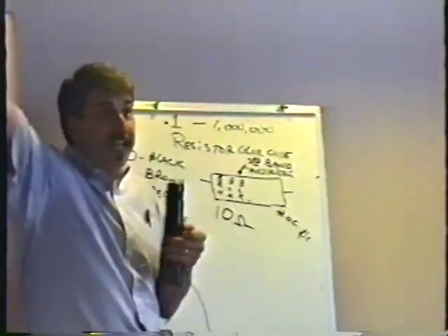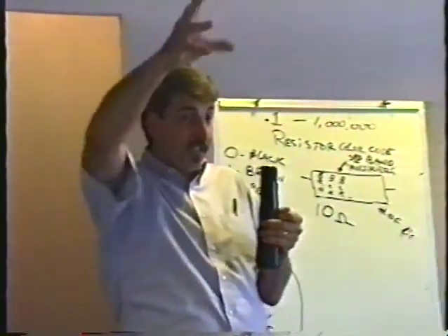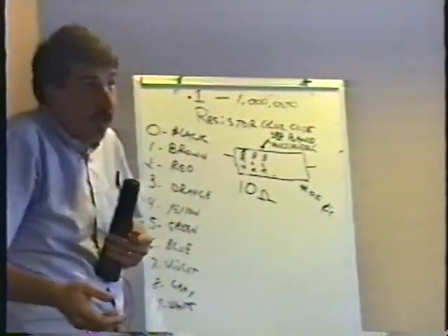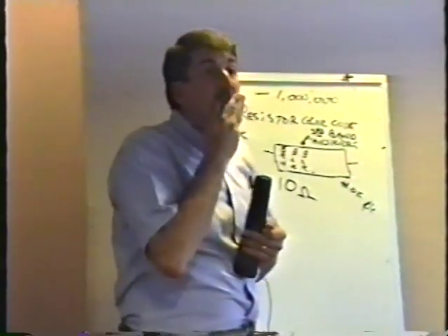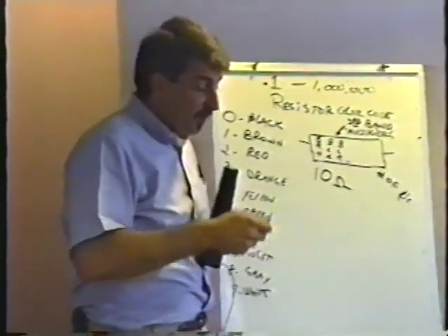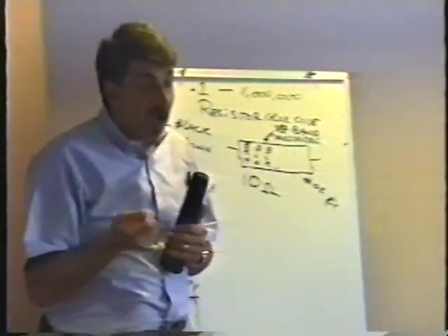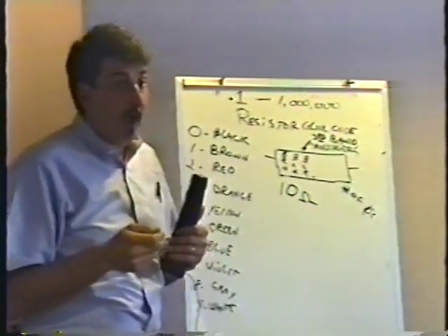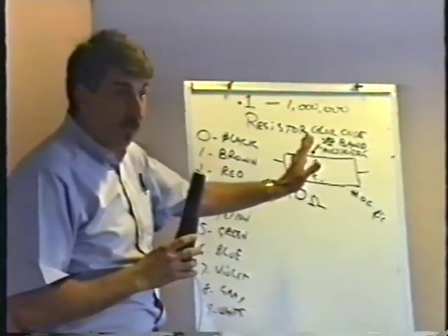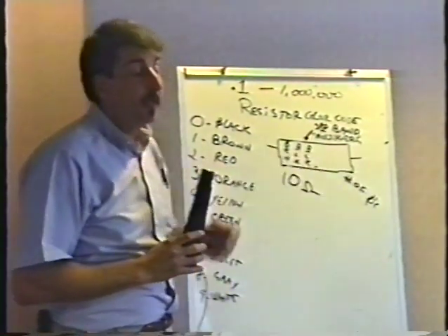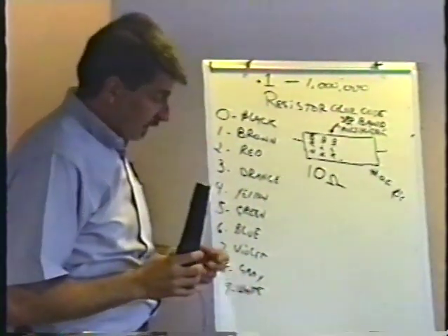They go, oh, I'm a genius. I found it. This resistor's partially shorted. It's supposed to be 100 ohms. It's only 10 ohms. So you boogie over to Radio Shack, and you get a 100 ohm resistor to put in there. You may not notice that the colors are different. You know, it'd be brown, black, brown, wouldn't it? If it was 100 ohms, it'd be brown, black, brown. So you may not notice that the colors are different.